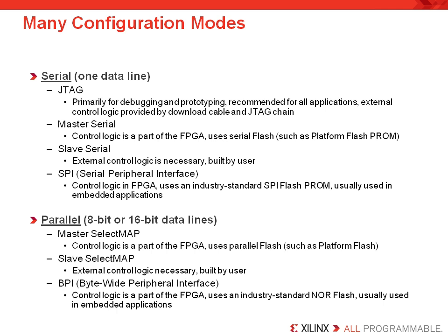Now, first of all, configuring with JTAG is most frequently used when debugging a design. It is always recommended that customers include a JTAG configuration path so they can debug their design and system. No external control logic is necessary since the FPGA has a built-in JTAG chain and the external control logic is provided by the JTAG cable.